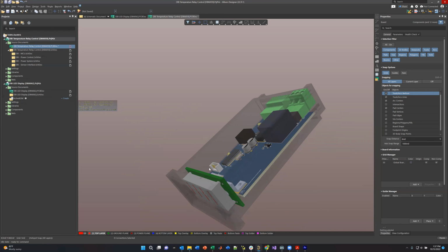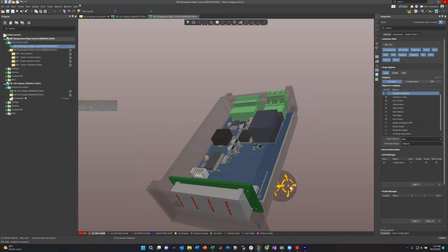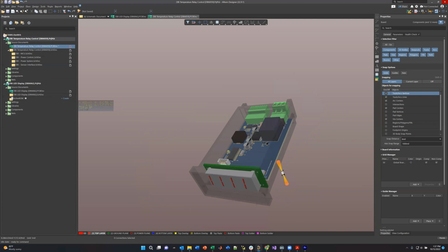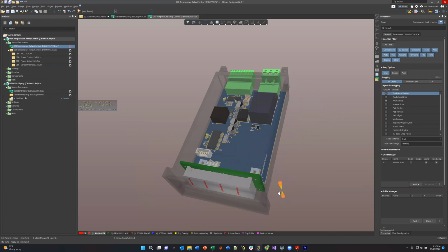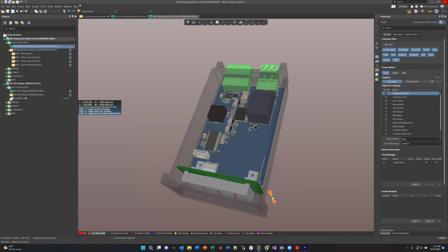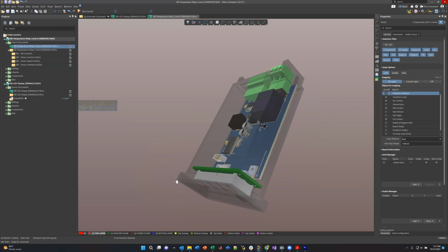In fact, when we built the prototype and put everything together, other than tweaking a little bit, we had to remove a little bit of circuit board material here because the dimensions for the box versus what was in the data sheet were off by like 2 millimeters, if that. It just made it, and so we just had to shave the board a little bit to slide it into the box. Other than that, it fit like a glove.